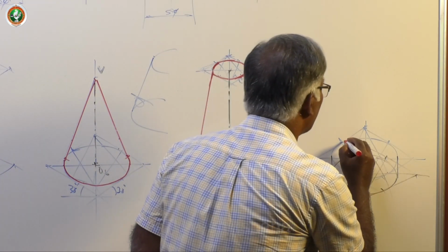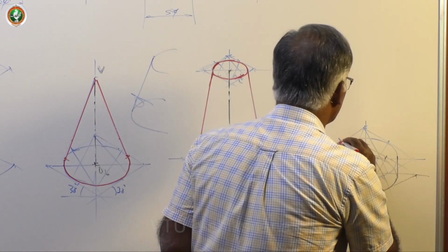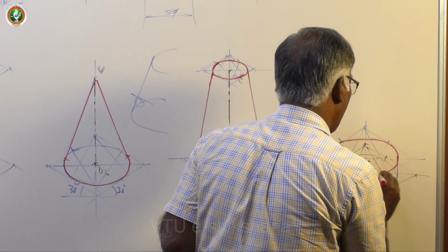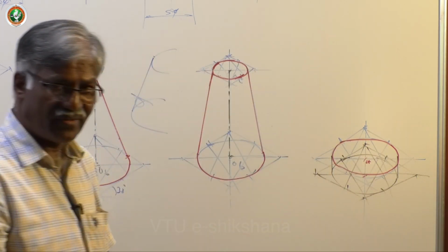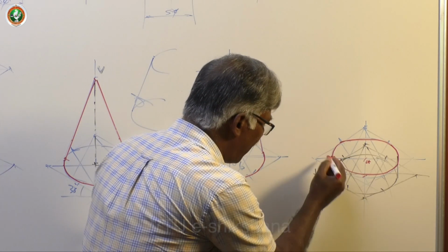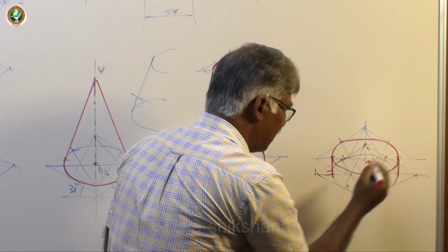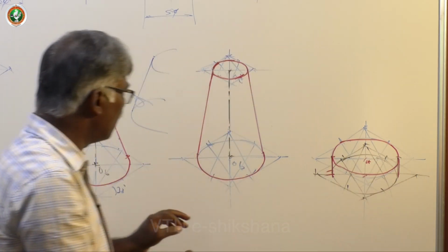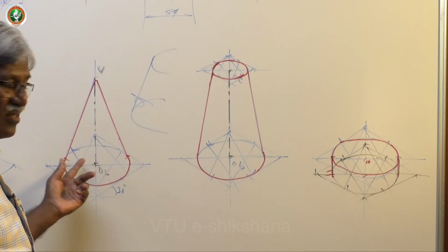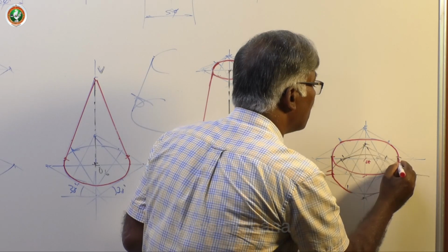So, let me try my level best to make it dark with smooth curve. Okay, this is top face, ellipse. Then this tangent point. Yeah, this is tangent point. Till that point you draw vertical line. No question of this tangent going above the major axis as in this. It is exactly the same major axis points. Now draw smooth curve.